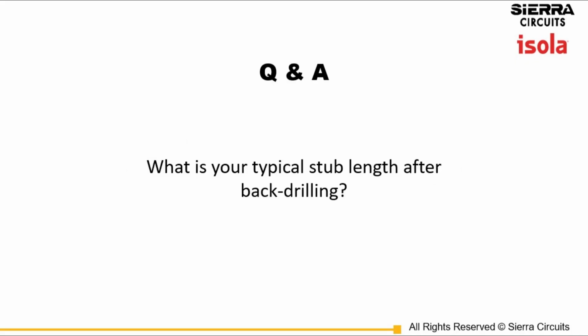Thank you. And follow-up question from Stefan. I think this is for you, Steve. What is your typical stub length after back drilling? We don't really have a typical length. It really depends on layer count, how thick the board is, how many layers that we can basically disconnect. That's usually specified by the customer. We do have advanced drilling equipment with electronic feedback systems, so our depth control is plus or minus a half a mil. So really, it's just whatever the customer specifies on the remaining stub.